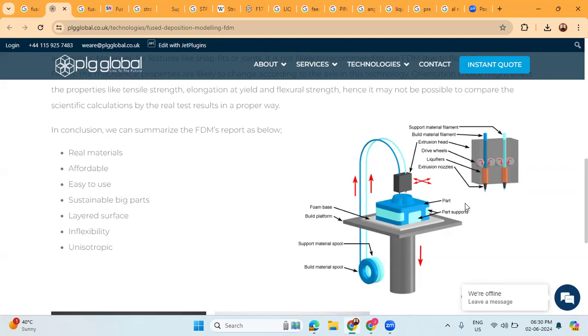Resistance heating involves passing an electric current through the wire, which heats up and melts the material as it is fed into the machine. Induction heating involves using a magnetic field to heat up the wire, while arc melting involves using an electric arc to melt the wire. Energy beams, such as either laser beams or electron beams, use a concentrated beam of energy to melt the wire and form the finished product.